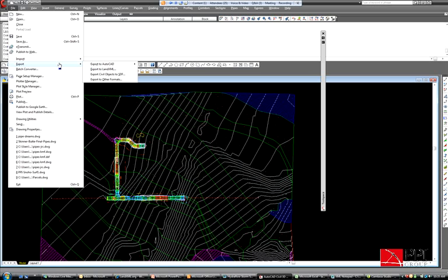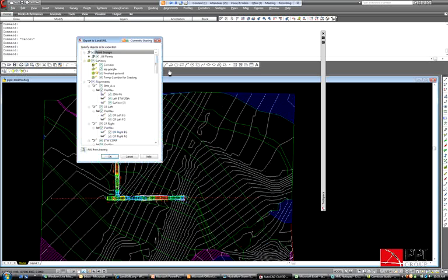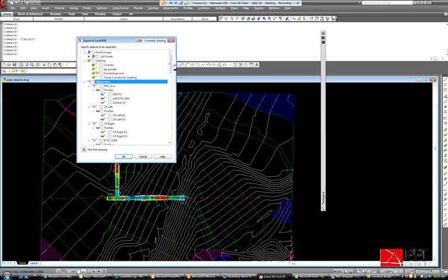So I'm going to come to the File pull down and export to land XML. Like I said, that same menu, you come out to SDF and bring yourself into the HEC programs as well. And in here, all I'm really wanting to bring in is the pipes.